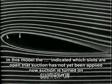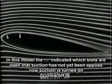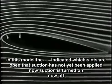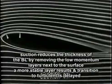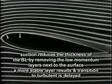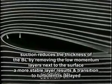Now suction is turned on. Now off. Suction reduces the thickness of the boundary layer by removing the low momentum layers next to the surface. A more stable layer results, and transition to turbulence is delayed.